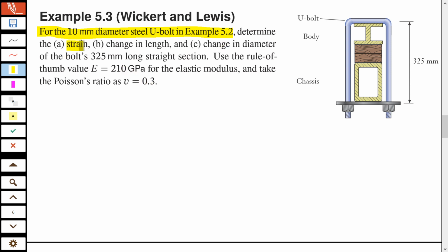So what we need to find is the strain. Yeah, then we need to find the change in length, which means the deformation, and or you can also call it elongation. And we also need to find the change in diameter. और length उस example में नहीं था, यहाँ पे length given है. ठीक है,